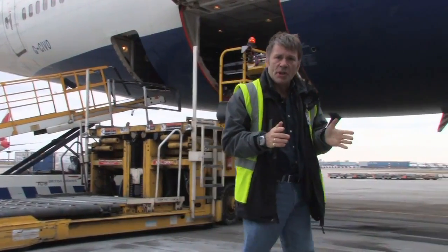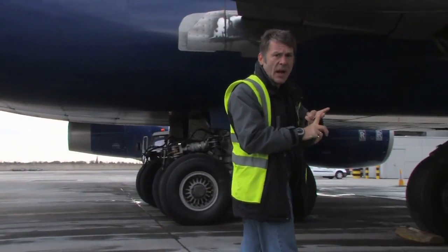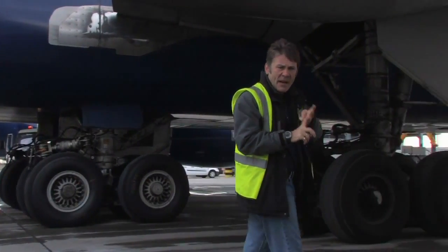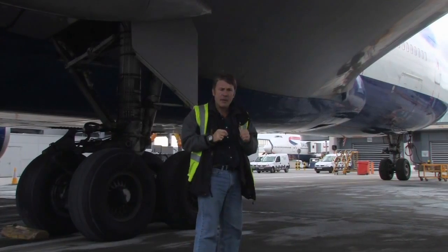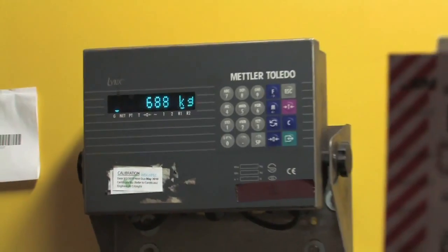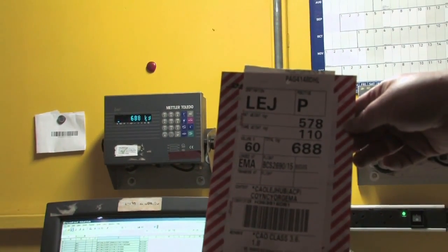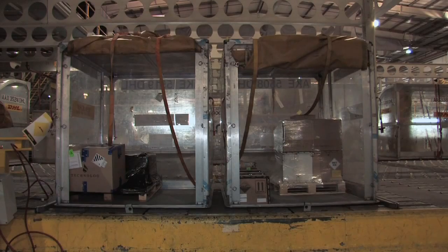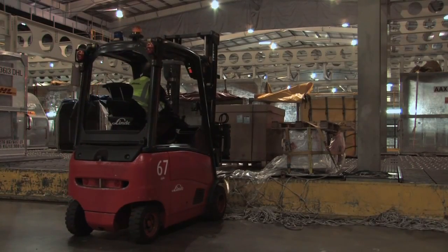Now, if dangerous goods are carried aboard the aircraft, it's important, one, they're labelled correctly, they are securely stowed, and they're stowed the right way up. In addition, something called a NOTOC, a notification to the captain, is going to be given, and that's going to be given up there. Dangerous goods must be packed, loaded and secured in the proper manner. Otherwise, they may become a danger to the aircraft and everyone on board.